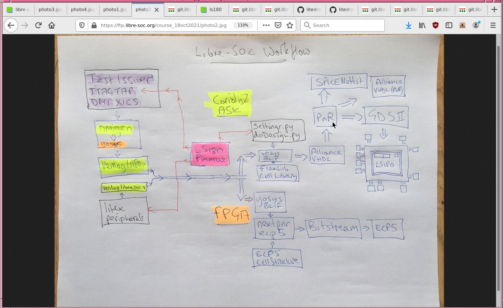After the place and route, which takes over an hour to 90 minutes, you end up with a netlist, which again you can extract and end up with this VHDL subset, but it will be at the gate level, or cell level, of connections to the cells, and consequently that cell library is an important input into this phase here, which is where you pick up the logical representations of the cell library in either Verilog or VHDL, and it's why you have those.